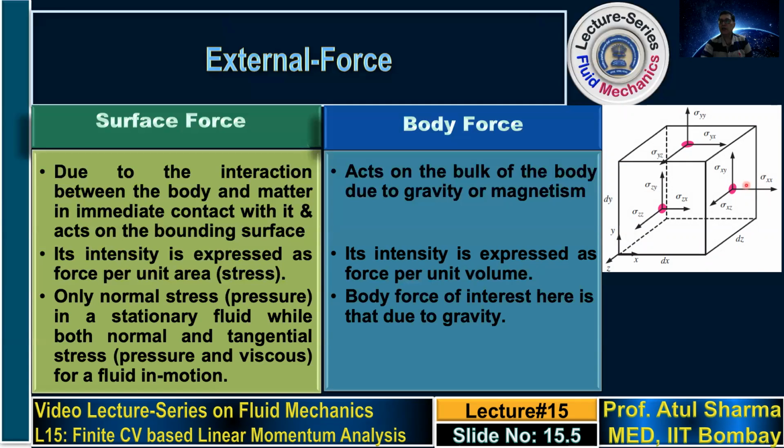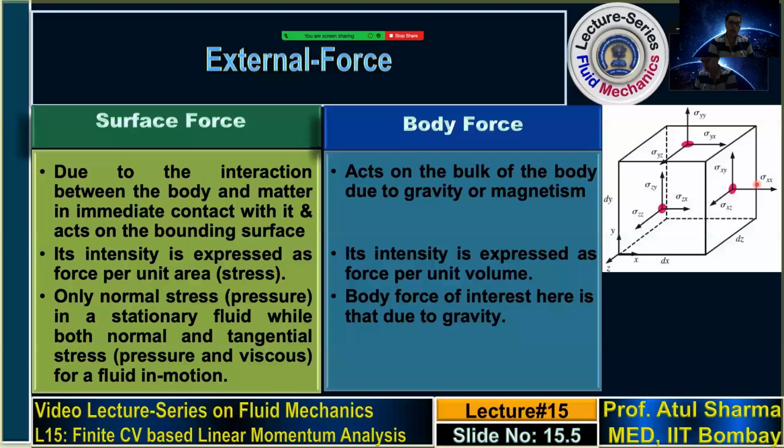So let's call this sigma the viscous stresses. Other than this, you will have pressure also as a stress, a surface force term as a stress. So if these are the viscous stresses, I will show you the pressure separately. The pressure always acts normal to the surface. So it will act in this direction. On this surface it will act. Pressure is always normal and compressive. So these are the directions of the pressure forces.